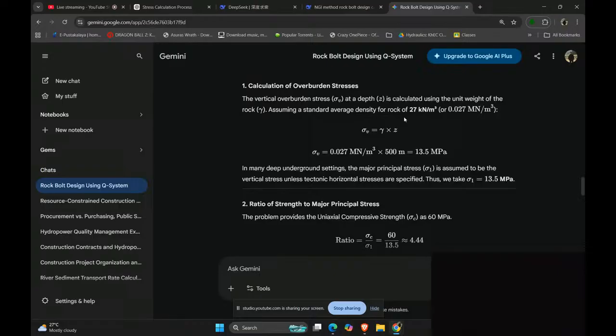Similarly, RQD is stressed after the blasting around the tunnel and drops to 35 percent, resulting in an RQD of 35, so the value of Q dash for equivalent dimension D of 6.25 places the excavation inside category 5, which